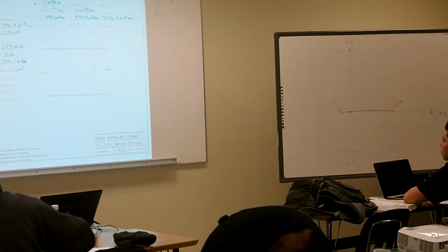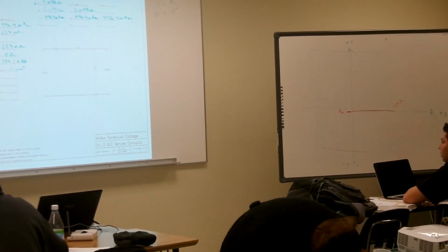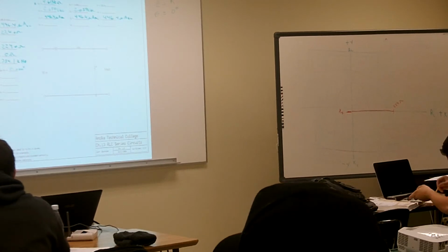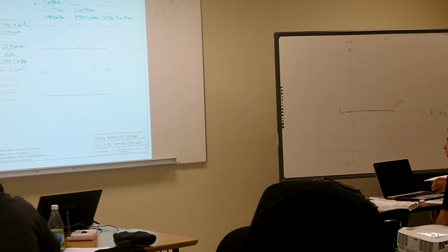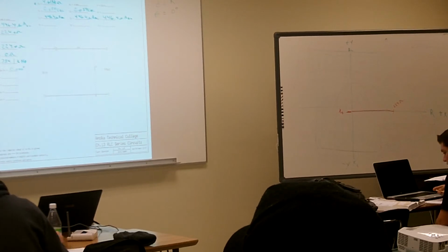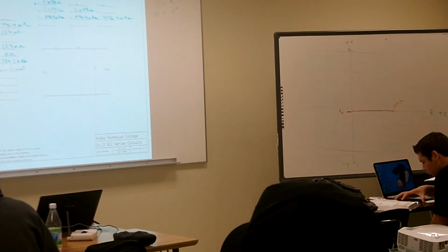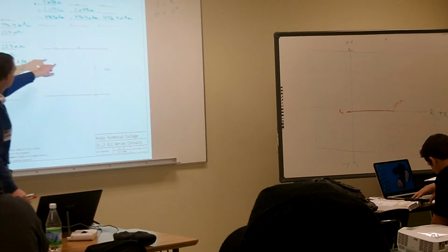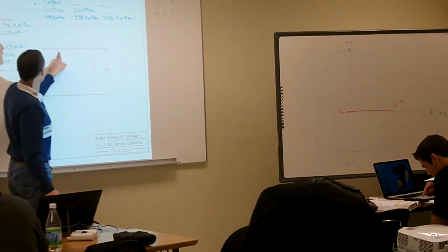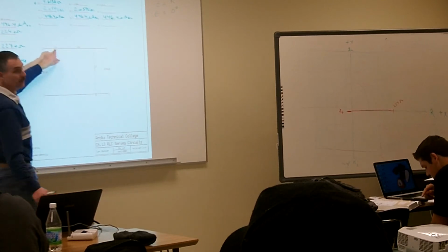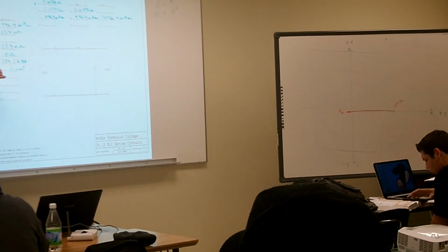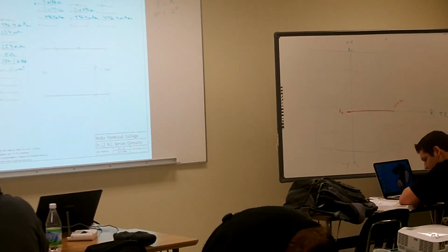What do we have for our source going in? What's our voltage source? 100 millivolts AC. So did everyone get 2.059 volts? That is correct. That's exactly what's going to happen. Remember, we were talking about when you light up your neon light bulb, when you collapse the magnetic field across that inductor, that light flash took around 80 to 120 volts to light up that neon bulb. When that inductor started collapsing, it induced a large amount of voltage. Then that capacitor absorbed that voltage and stored that energy. So it does indeed end up equaling over 2 volts, even with just 100 millivolts in the circuit.